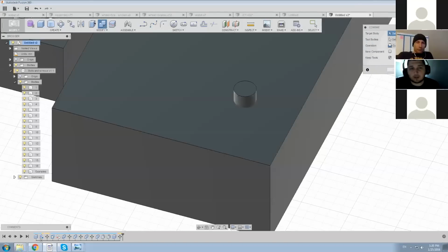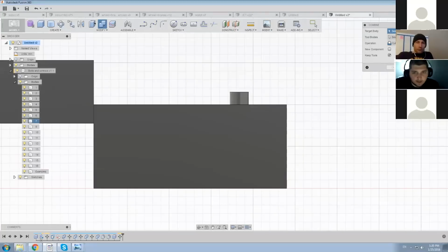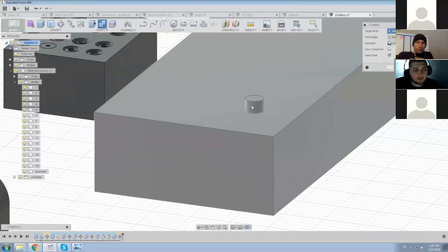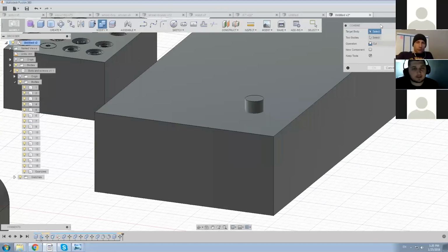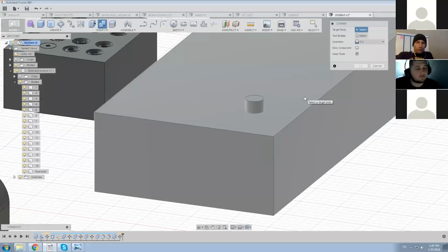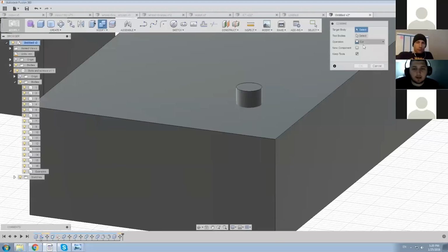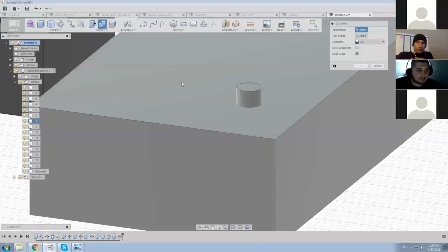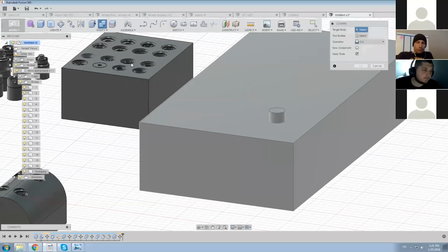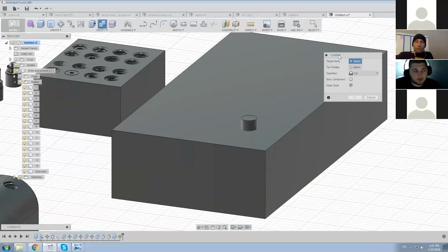But more than that, you can even reuse stuff like this. A Boolean operation in Fusion 360 is called combine. You can see that I have the main shape here, and I have placed the shape that I will be cutting with. You have to think about it as you would in the real world, let's say with clay and a piece of metal. You take that piece of metal and you stamp it into clay, and it will leave that stamp in the reverse shape of the design. So this operation works really easy.